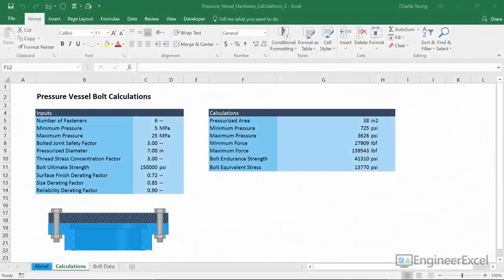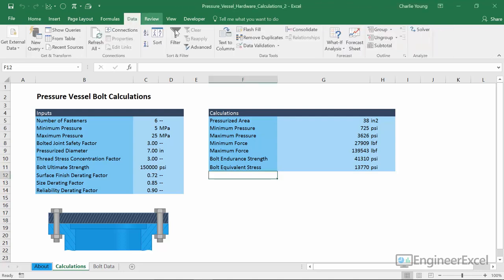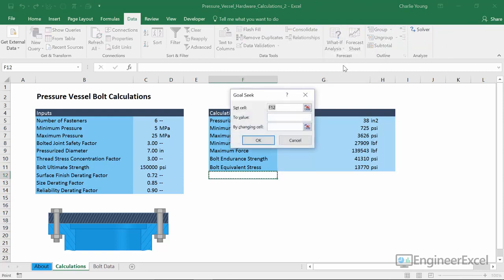So like I said, that area is showing up in the first 2 equations in this system of equations, and to solve that system of equations for area, we're going to use a tool that's built into Excel called GoalSeek. Now GoalSeek can be found if you go up to the Data tab, and then in the Forecast selection, open the What If Analysis drop-down and select GoalSeek.